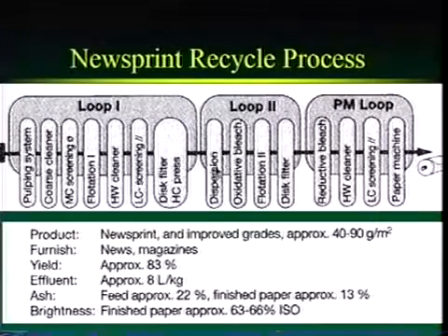At that high consistency, we talked about bleaching. If you apply bleach at a higher consistency, you'll get a better response because you've got a higher effective concentration of bleaching chemicals. So in this case we're going to do oxidative bleaching, maybe peroxide. Then we're going to do flotation at a lower consistency. This must be done at low consistency.